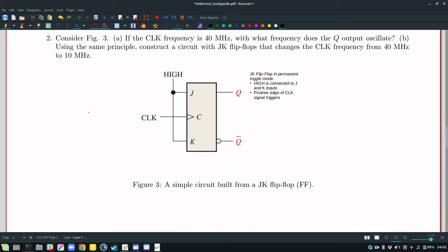Well, let's keep in mind, if we do that same timing diagram as before from the last problem, remembering that this is a device which is toggling on every positive edge. Well, some of the edges are positive and some of them are negative, are falling edges. So if there's the clock, then this JK flip-flop will, let's say, toggle to 0, and then toggle to 1, and then toggle to 0, then toggle to 1 again, and then toggle to 0.